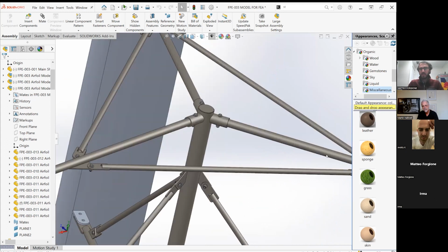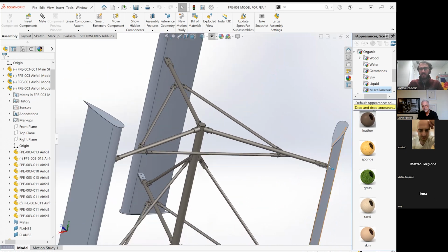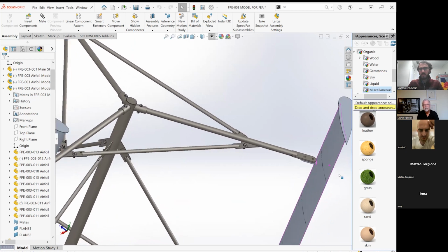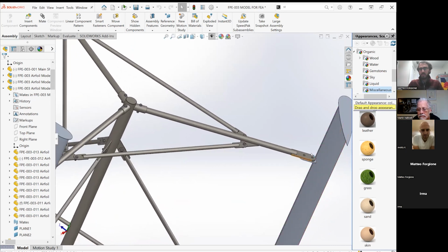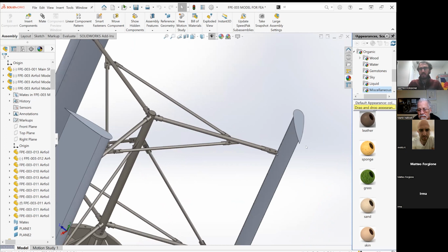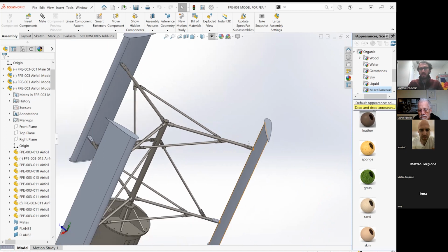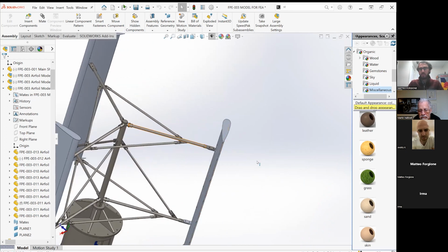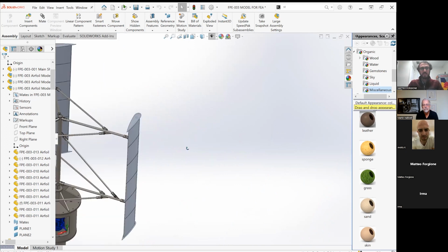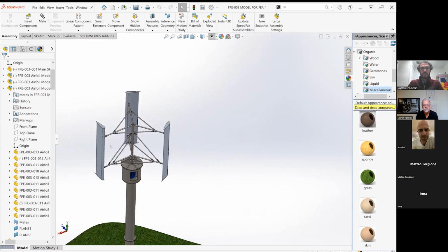So that's all just bolted together. And then because we're not socketed at the end connection and we have this lug basically coming out of the airfoil, we have two bolts there to take care of the fact that the force is not always, like an airplane wing, in some lift direction, let's say to the right in this case, and be pulling on those. In this case, it could be in any direction. So you're going to have a torque around that joint, which is why I have 2 bolts to take that. And they're pretty decent size there to make sure that we can take the torque without any fatigue issues.